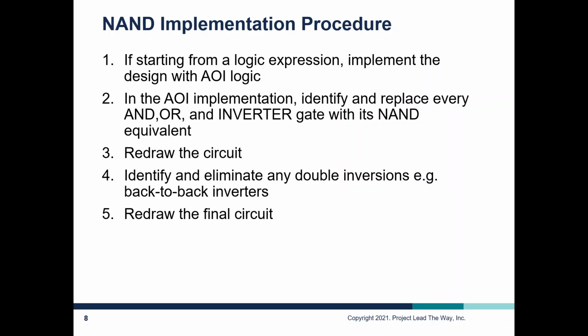To implement a NAND circuit, we do these 5 steps. We start with our logic expression, and we go ahead and implement the design with the regular AND or inverter logic. In the AOI implementation, we identify and replace every AND or an inverter gate with its NAND equivalent.